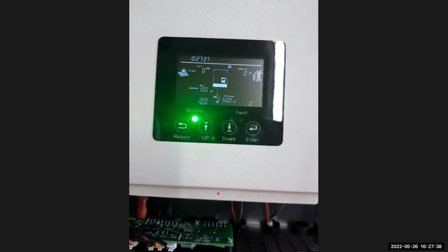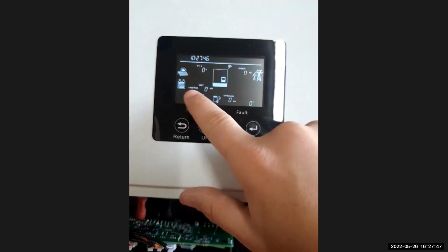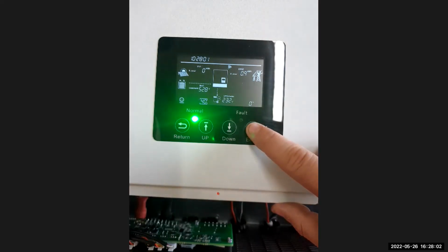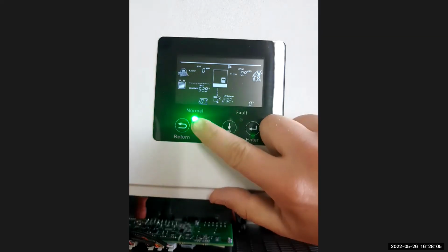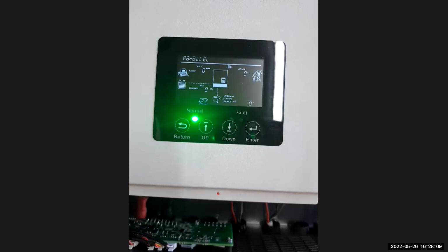As soon as you press enter, you'll see your machine will switch on and off. When it goes on and off, you'll see on the battery information here that you have to see a value there before you know the machine accepts your battery. If you have a lithium battery and it does not communicate, it won't show any value in this box. Now, from the battery settings on, the next important setting is setting number 21.